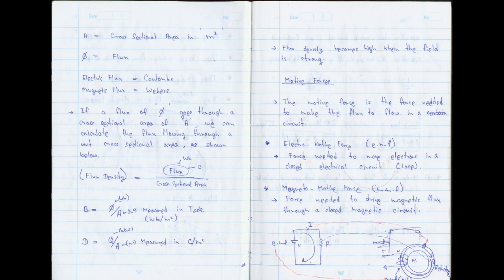If you could not do it, maybe you have studied magnetism, but in isolation, without comparing it with electricity. The electric circuit, the magnetic circuit: look at how similar. You have electromotive force, and here you should have magnetomotive force. Magnetomotive force is measured by the number of turns multiplied by the current. Then you have current here, and corresponding to that you have flux there. Electromotive force, magnetomotive force. And you have resistance there, and corresponding to that, in this material, you have what is called reluctance. This is reluctance. Magnetic materials all have reluctance, whereas electric materials have resistance. So you can see how similar electric circuits and magnetic circuits are.